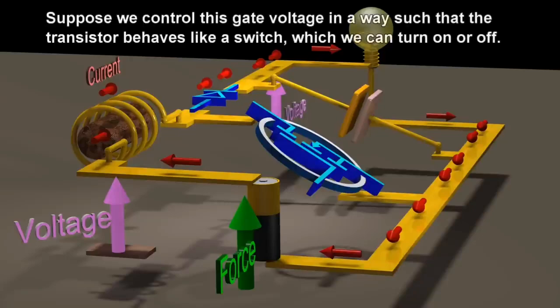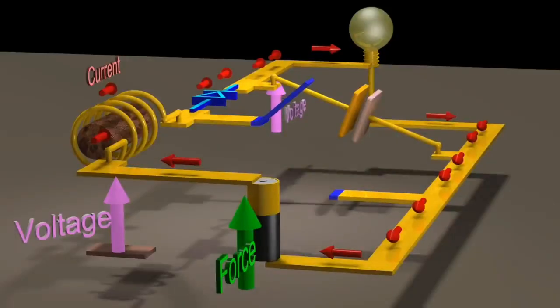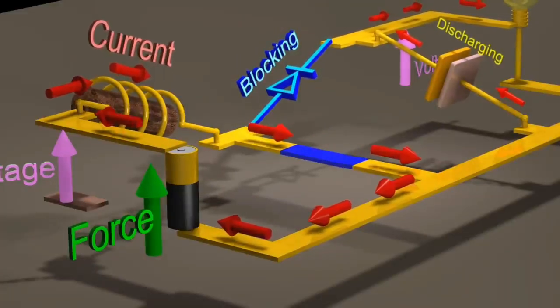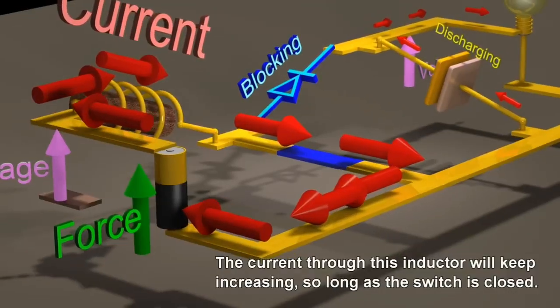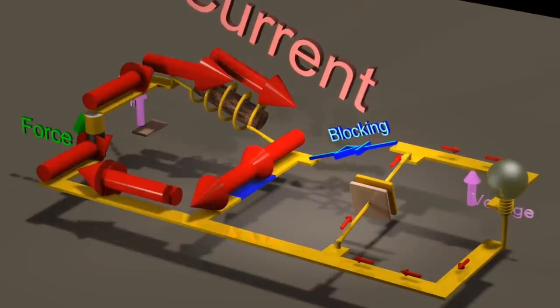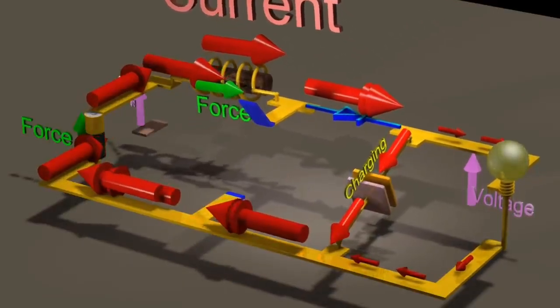Suppose we control this gate voltage in a way such that the transistor behaves like a switch, which we can turn on or off. If we close the switch, we will cause a DC voltage to appear across the inductor. The current through the inductor will keep increasing so long as the switch is closed. The current through an inductor cannot change instantaneously. Therefore, the moment we open the switch, the inductor will create a force causing the current to continue flowing.